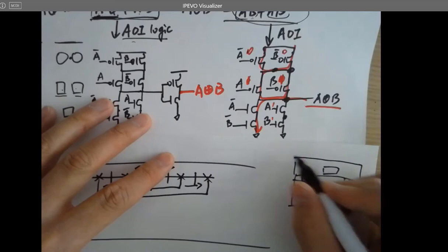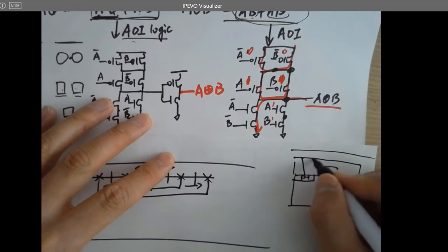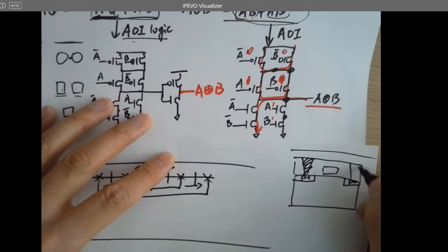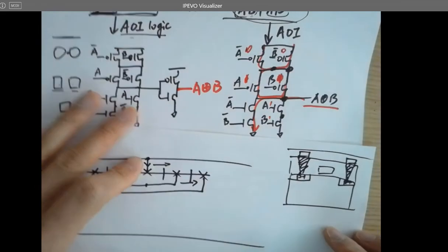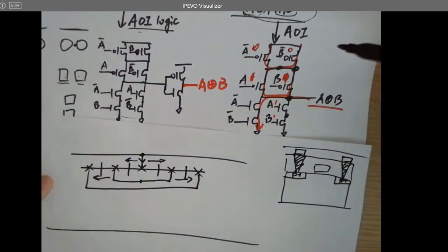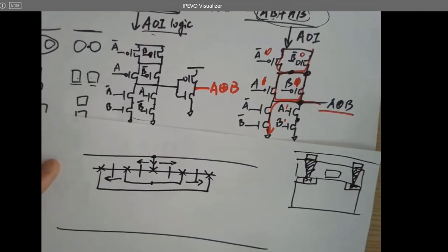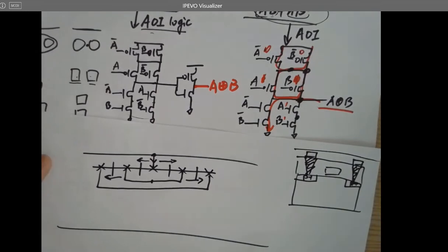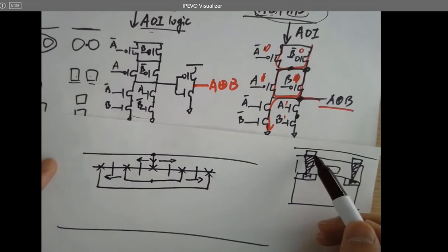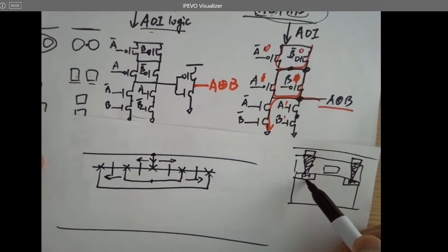So what's happening here is it has a via and has a metal 1. Metal 3 is on the top to connect to all the bonding, the frame pads for the chip, right? Metal 1 is at the bottom, being directly shorted to P plus.